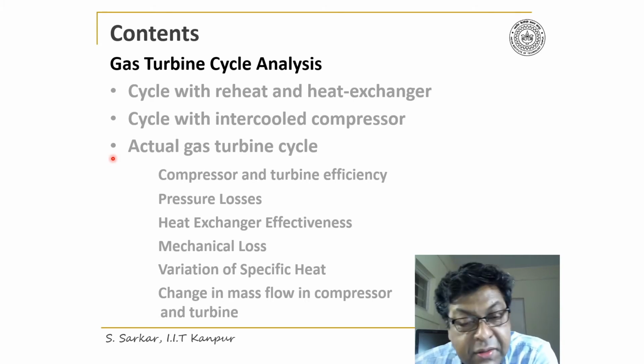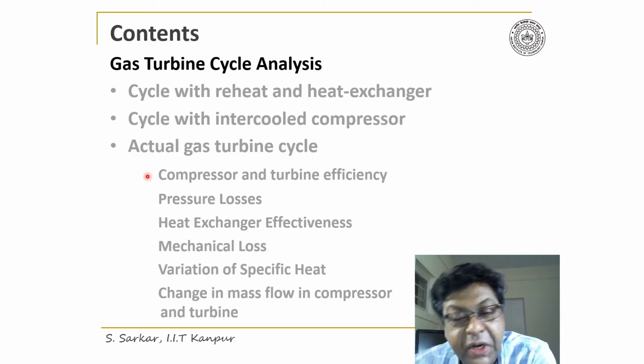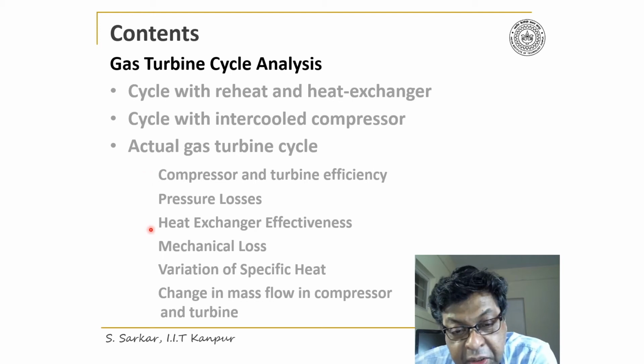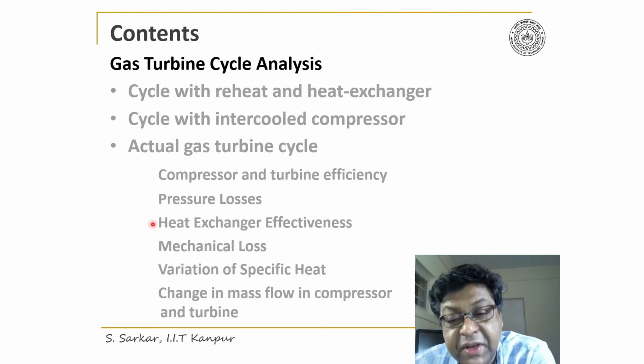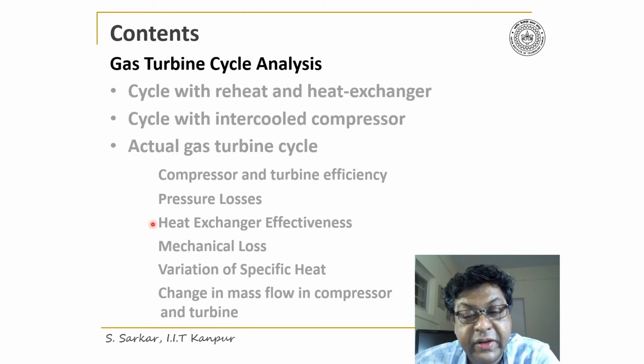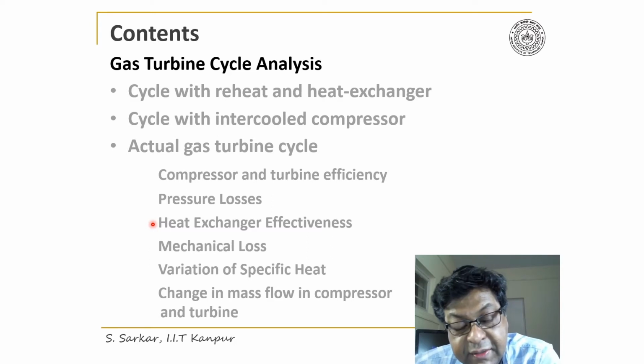We'll consider the compression and turbine efficiency, pressure losses in the heat exchanger and combustion chamber, then heat exchanger effectiveness, so it will now be considered not perfect. Furthermore, we'll discuss mechanical losses, variation of specific heat with temperature, and changes of mass flows in turbine and compressors.